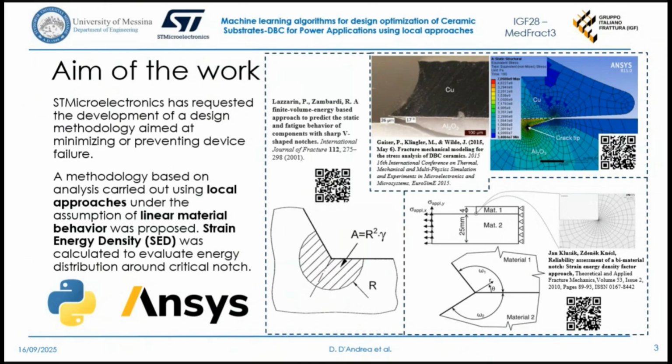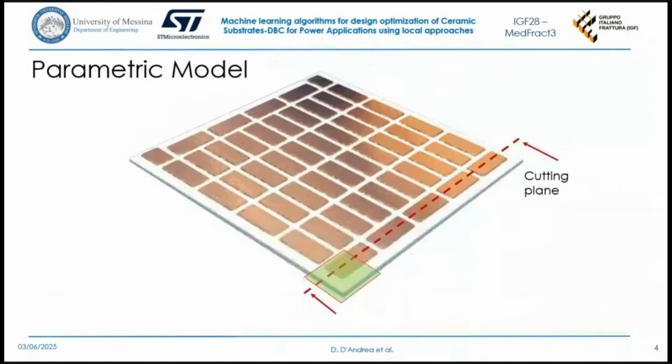in the ceramic layer. And in this work, the copper contribution to the failure is treated like an external load. So we also found a work by Klusak in which they treated the interface between materials like a welded joint, and by doing so, they applied the strain energy density methodology to investigate the critical area around the notch. So we proposed this methodology to ST Microelectronics and used two different approaches.